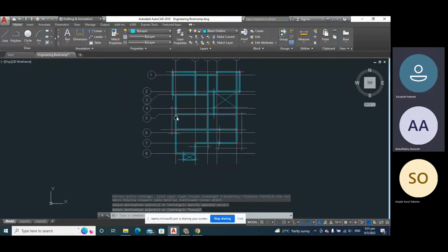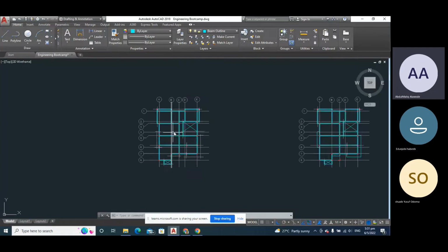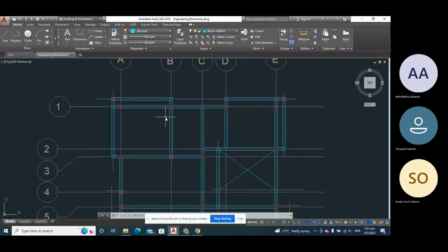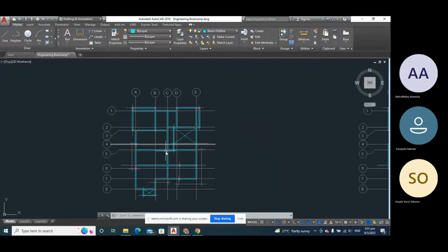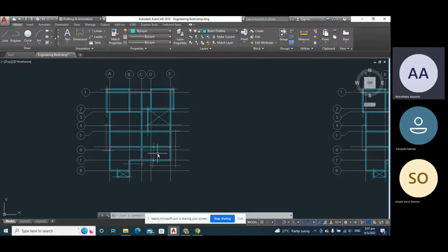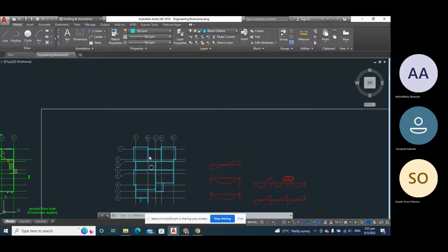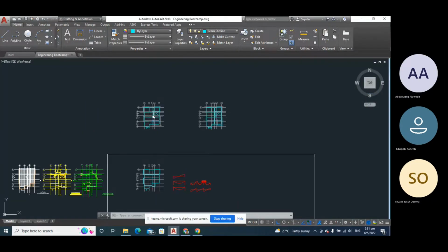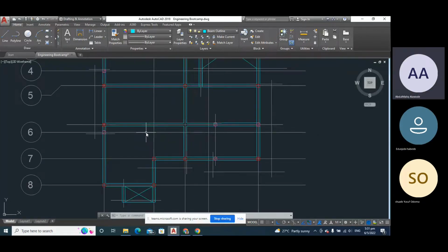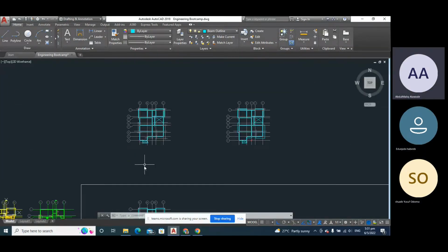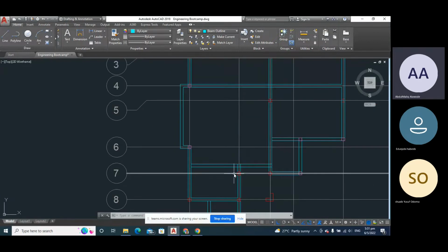With this we have all our structural elements, slab, beam, and column, on the first floor layout, and they all have grid lines. Other things that we are going to create, we are going to be measuring them. If there is need to create more grid lines in the software, we are going to measure with reference to any of the existing grid lines when it's time to model them.